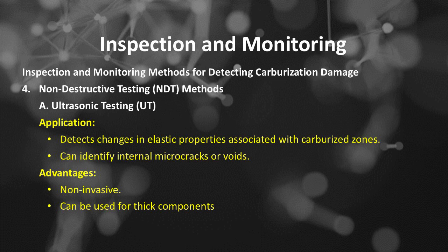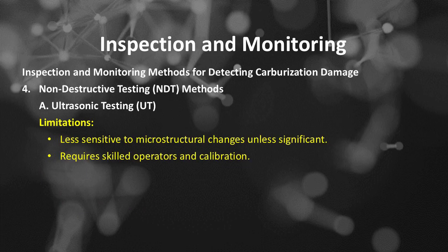Advantages of UT: non-invasive. Can be used for thick components. Limitations: UT is less sensitive to microstructural changes and less significant. Requires skilled operators and calibration.